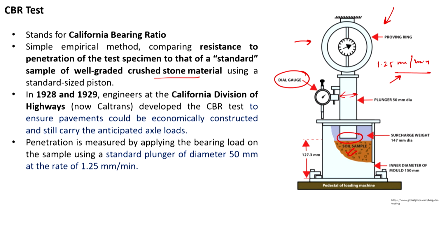So, it will continuously give us readings of how the height of the sample is changing with the increase in the penetration. Okay. And the load is applied using a load cell here, and the value of which can be monitored again using a dial gauge on this particular proving ring. Okay. So, more details about the test method we are going to talk about in this particular presentation.